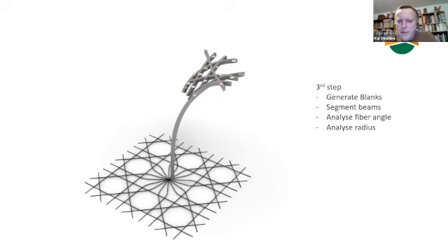And in the third step, we do an analysis of the curvature of these beams. And this is, I think, one of the key points and the most important point to really understand the project and get it in costs. Because what we need later, we need wood which is bent directly in the direction of the member. Because we can only pass forces into the wood along the fiber, not across the fiber. So finally, we have to bend the wood exactly in this direction.